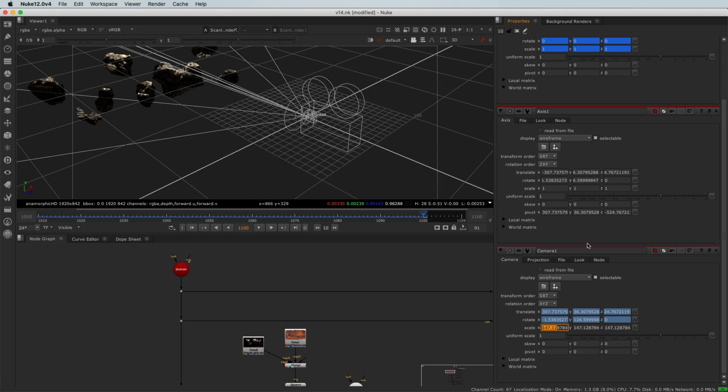So what I can do is come to my axis and modify the uniform scale instead of modifying X, Y, and Z here. And I need to invert the scale. For that, I will do 1 divided by, and I can type my formula here, paste the value with Control V, and hit Enter. And it will find the actual scale that I need to transform.